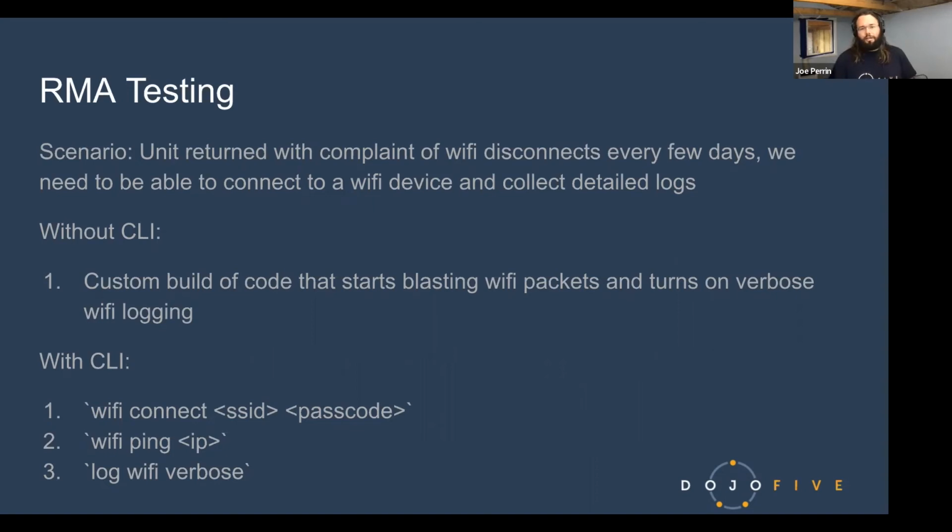And then logging, right? So maybe this gives access to your logging mechanism, which hopefully you also have in your embedded system. But you turn on verbose logging, and there you go. And that would be great, again, for you, for hardware. It's like, hey, we're running into an issue. Okay, log accelerometer verbose, log Wi-Fi verbose, whatever logging system you have, be able to up the logs when you're looking for a problem.